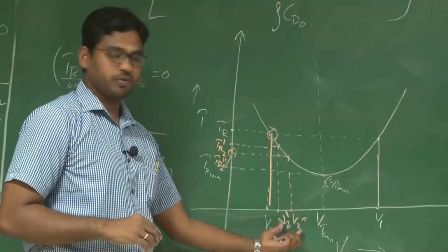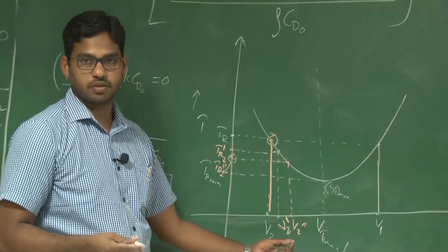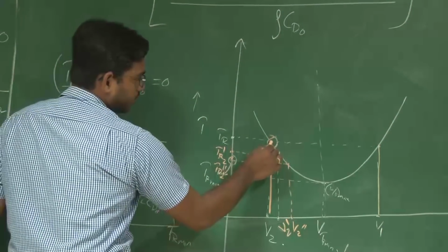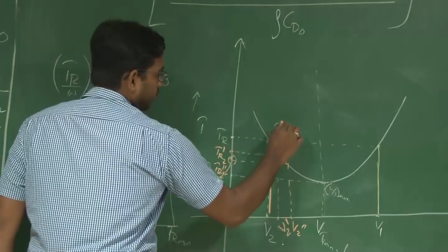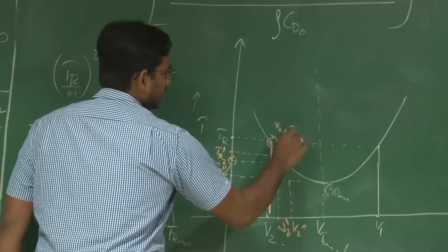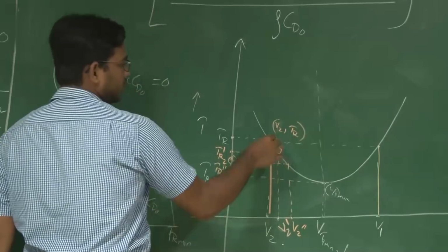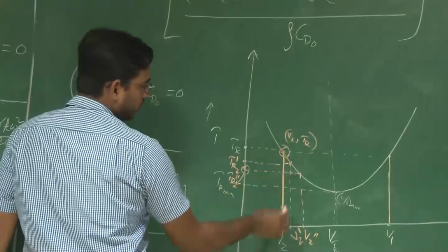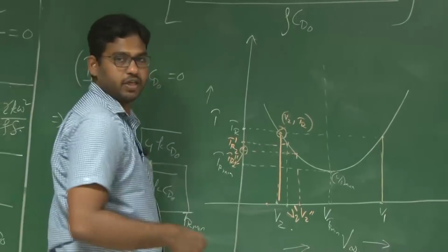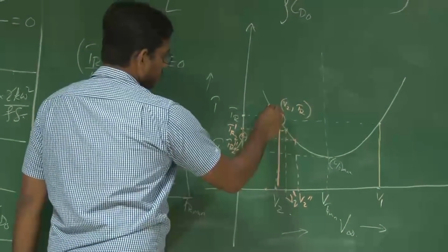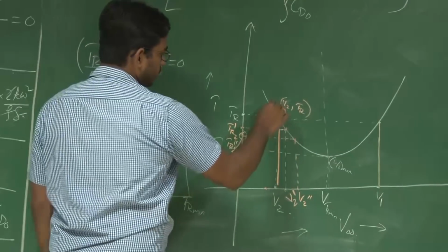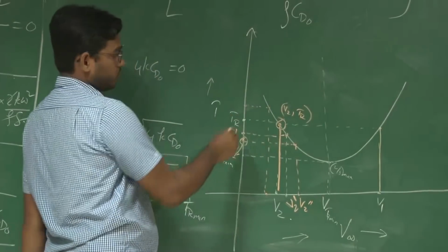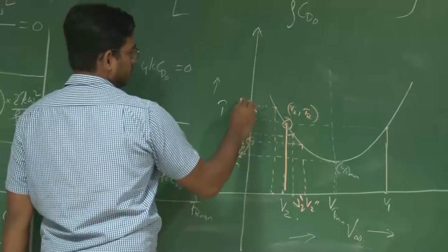Now say we assume that there is an increase in velocity because of the disturbance. Now say there is a decrease in velocity because of the disturbance. So again we have come back to our original equilibrium. Say this is my v2 comma Tr, the corresponding coordinates of this point, right. Now say the velocity has reduced because of some external wind disturbances, right. Since we are not touching the throttle here again, this reduced velocity will result in an increased thrust requirement.